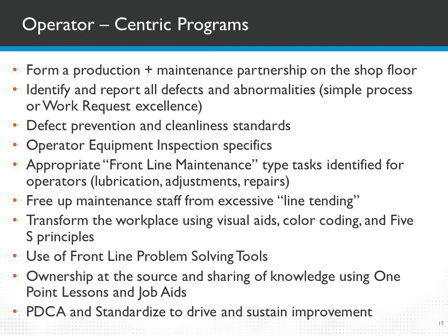5S and cleanliness standards are vitally important in this process. Identifying what tasks operators can do, as I mentioned, lubrication, filter changes, and inspections are all vital tasks that can be done by an operator. Operators can use visual aids, color-coded gauges, piping, etc. Cleaning goes a long way in helping prevent defects from getting in the way of production. It's been proven that this type of process increases production, and it also standardizes work.